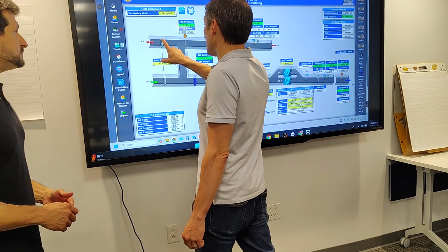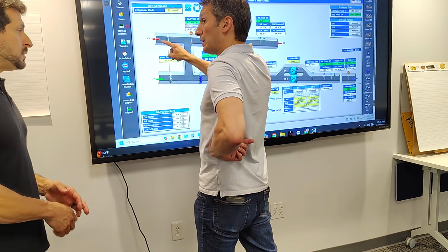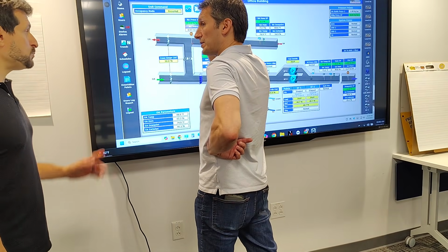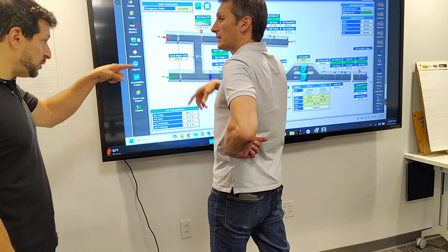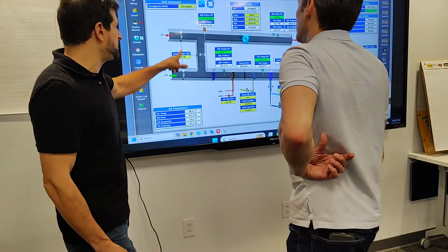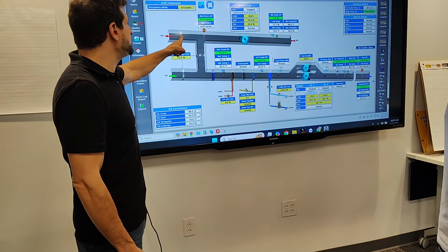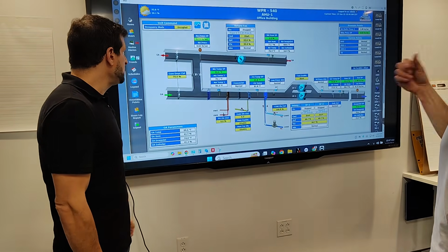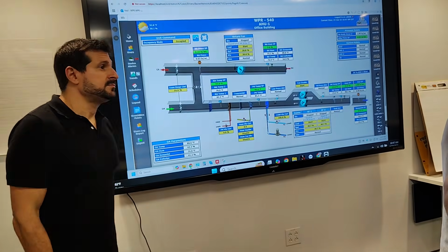I was telling him, can you close the damper? And he did it in one direction. And I said, no, you just opened it, and then he went back. That does not appear to be the way that it's currently programmed. All three of them are controlled by the same thing. So this one and this one match, and this one's inverse. So right now everything's 50. But let's say this is 20, this is 20, this is 80. And 50 is what's in the program, yeah. Okay. That's not overridden.